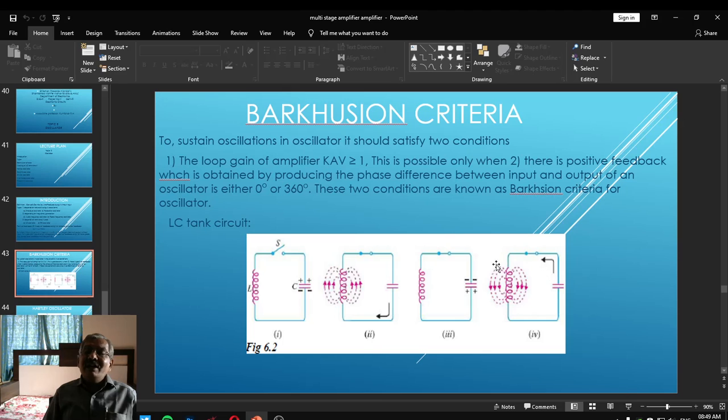That means di by dt becomes equal to 0. By the way, capacitor C will completely discharge through the inductance coil. The charge across the capacitor becomes totally 0. No charges will be stored in it. No electrostatic charges are present. The entire electrostatic charge is converted into the electromagnetic field, with the direction opposite to that of the previous one.